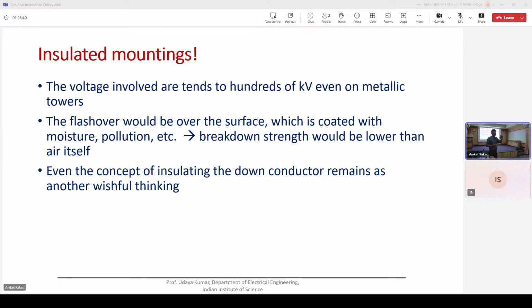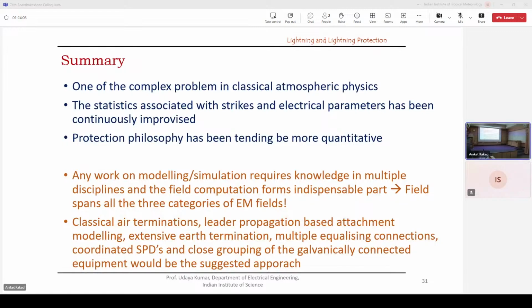And the other small one, the telephonic insulator, cannot take more than 33 kV. But it's a mental kind of satisfaction that I isolated the down conductor from the building. I don't think you can isolate the building using such small insulators. More than that, these insulators will have rain, moisture, pollution, so they will start conducting much before you think. So I wanted some time for discussion, so I thought I'd cover it very fast.